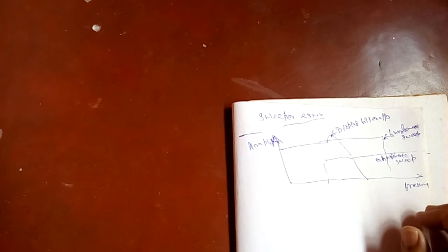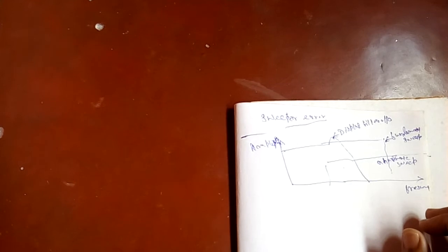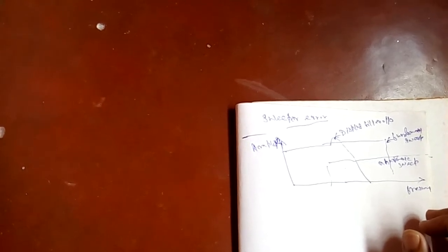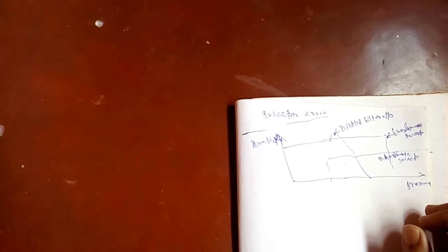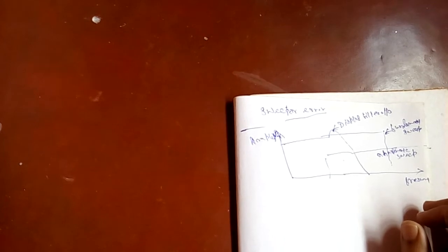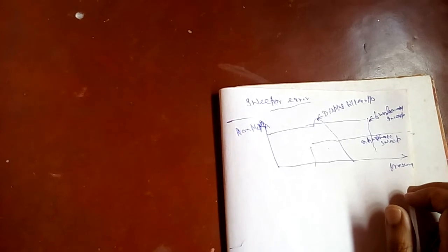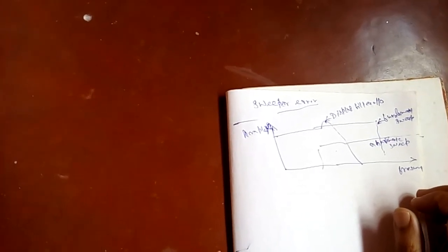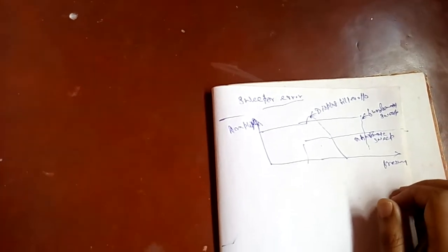So generally only the second and third harmonics are of concern; higher harmonics have much lower amplitude. The accuracy of the output and the change in the amplitude with the frequency is another important consideration. The amplitude varies with the sweep rate, since the amplitude feedback correction circuit has less time to work at faster sweep rates. So the output of a sweeper is not linear, which means the spacing between the markers is unequal. It is not equal. So it can easily estimate the value of the frequency using two markers.